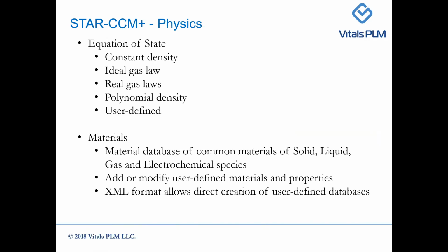For the gas equation of state, to model gas, we can specify constant density. We can use ideal gas law or real gas laws or polynomial density, or you can specify your own equation of state. And for materials, STAR-CCM+ comes with a huge database for different materials in all the three phases like solid, liquid, and gas, and some electrochemical species too. And we can add or modify user-defined materials and properties. XML format allows direct creation of user-defined database. So you can also create your own database in STAR-CCM+.